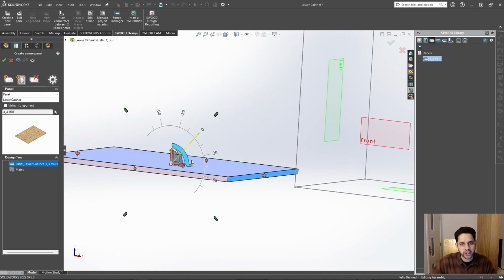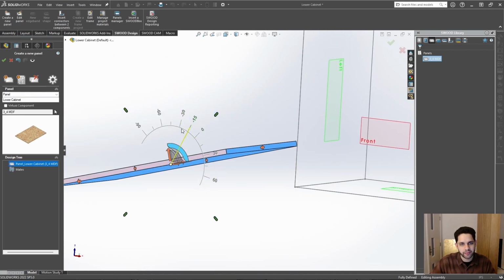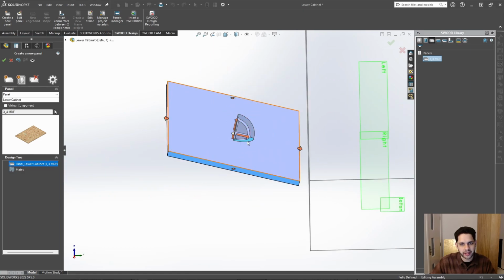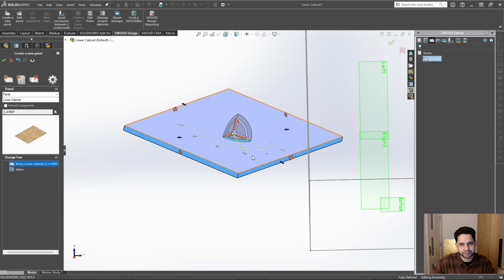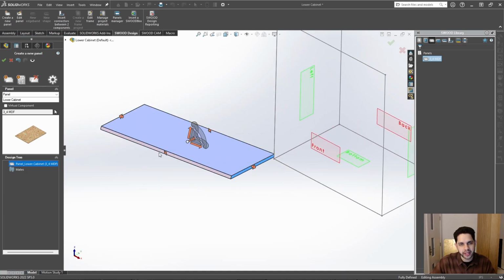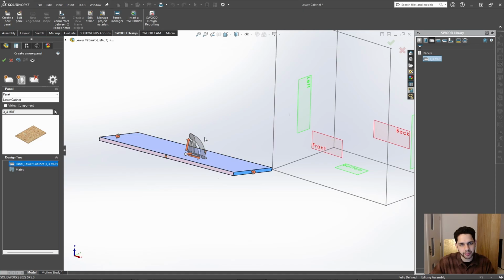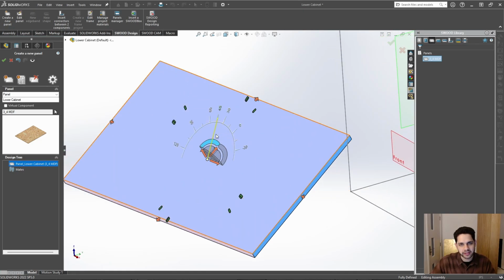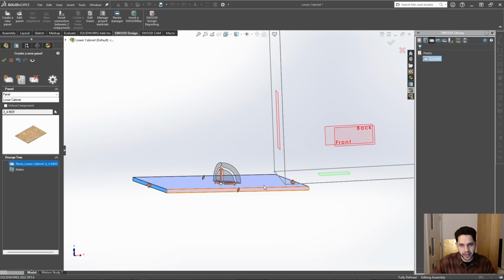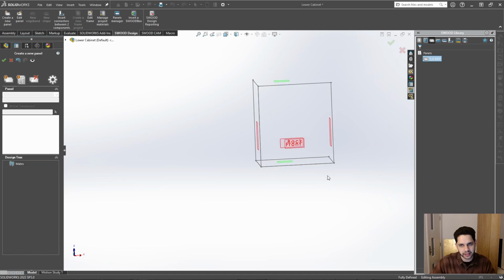You can also change the angle of the panel, whether it's this way, or this way. And then finally, you can snap these panels into place. Since I have this all wonky, I may just go ahead and delete this panel, which is, I'll select on it just like this, click this delete panel, and it's gone.